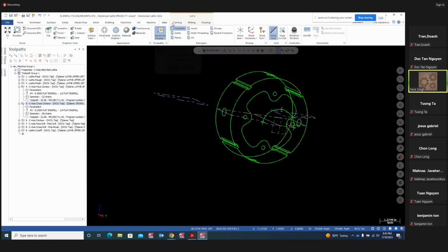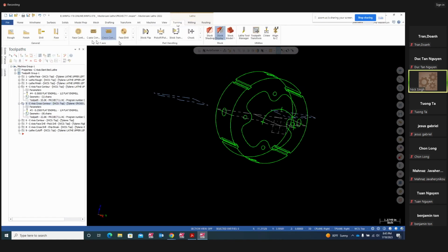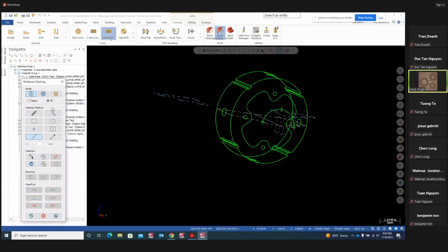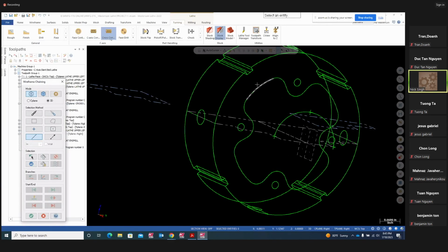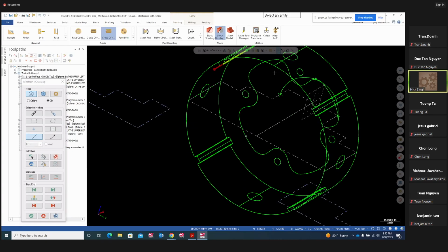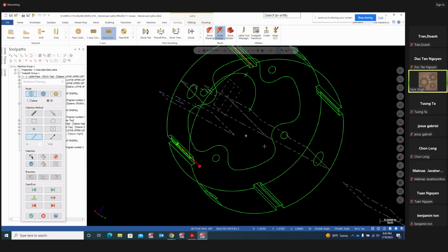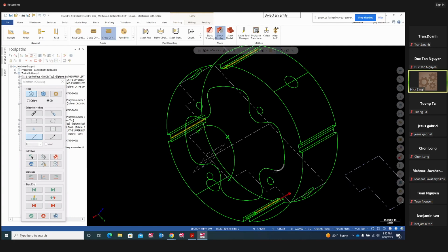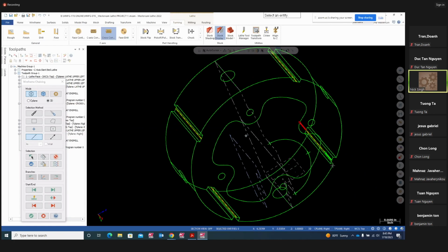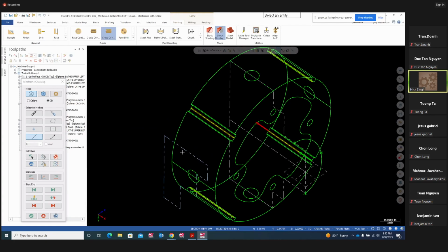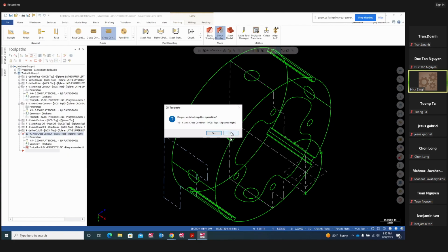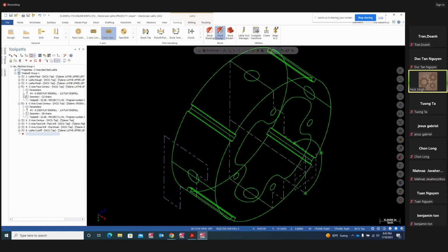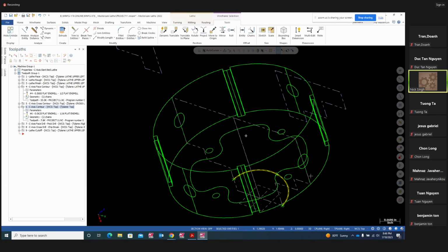So you do cross contour, you're going to go C-axis cross contour right here. You're going to pick the chain, pick single. So you're going to pick this chain right here, 1 right in the center, 2, 3, and number 4. So these are going to be your chains. So select those chains. And then comes your C-axis contour with a 1/16 end mill, which is going to be this guy right here.